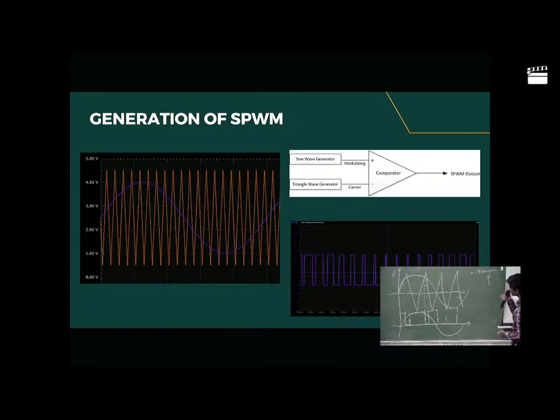How can you realize it's a low pass filter? This is a series inductance. In the Laplace domain, the impedances are omega L and 1 upon omega C. You know that any signal can be broken down into a number of components, as we see from Fourier. For high frequency components this inductor will have a very high impedance, and for low frequency components it will have a very low impedance. So high will be blocked, and low will be passed, right?